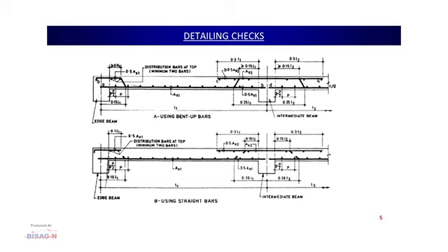Again, coming to the bending up of the bars, that is the main reinforcement, we have to ensure that 50% of the main reinforcement is taken inside the support, and 50% of the bars should be cranked up and taken to the top. The distance should be followed like 0.15 L, where L is the span of this slab. At 0.15 L the bar should be bent up and taken to the top. As such, the distance from the face to this bent-up portion should be at least 0.1 L, in fact more than 0.1 L.